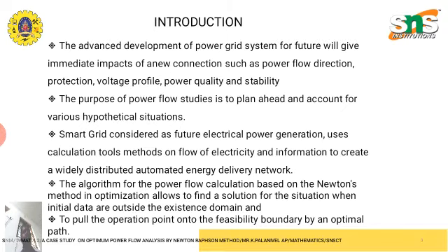The algorithm for the power flow calculation based on Newton's method in optimization allows finding a solution when initial data are outside the existence domain and pulling the power operation point onto the feasibility boundary by an optimal path.